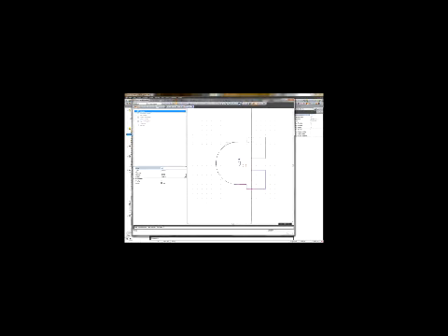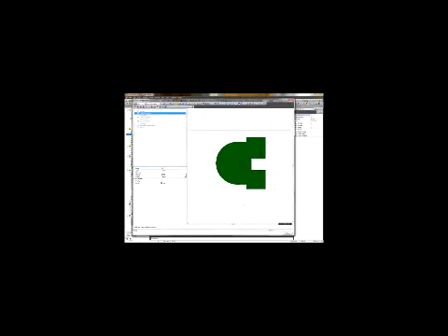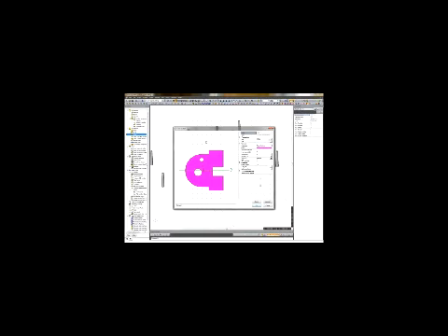In this example, we'll give our shape a green color so you can see it a little bit better on screen. In addition, we can use Boolean operations like add and subtract to help us create just the shape that we need. For this shape, we'll clip two circles to create voids in this cross-section profile. In addition, we could add analytical properties to our profiles.